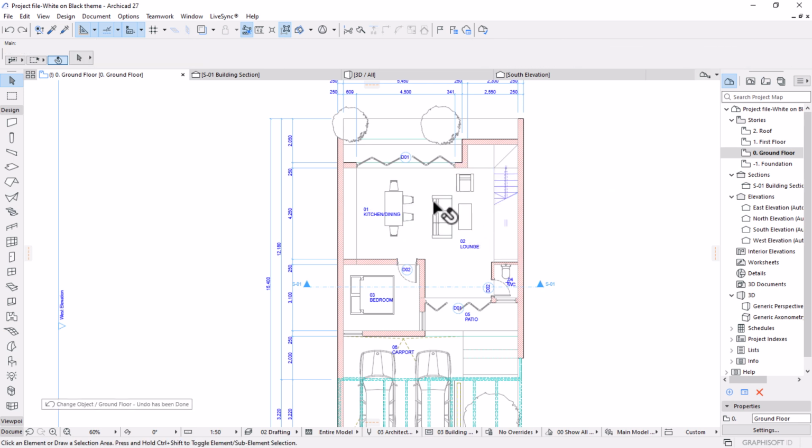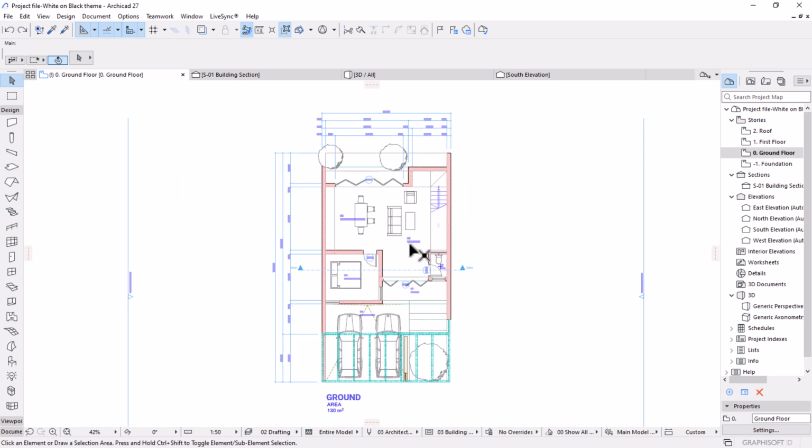But this will take you time, and again, it's not useful. What if you want to change instantly again to a different style? That will take you time again to redo it again. So you want a smarter way of doing things in ArchiCAD. In ArchiCAD, we are always seeking efficiency. So the best way is to use graphic override combination.